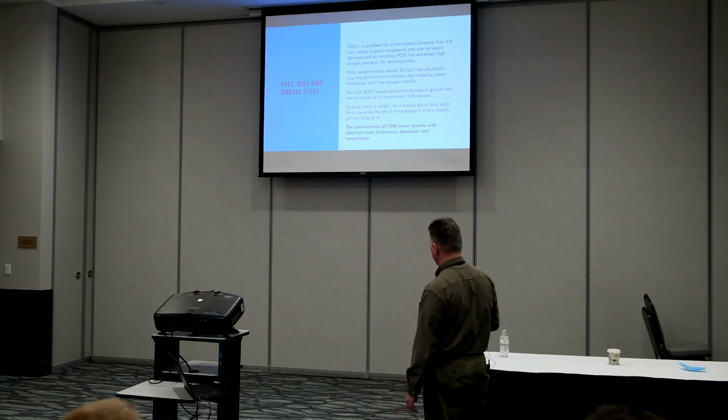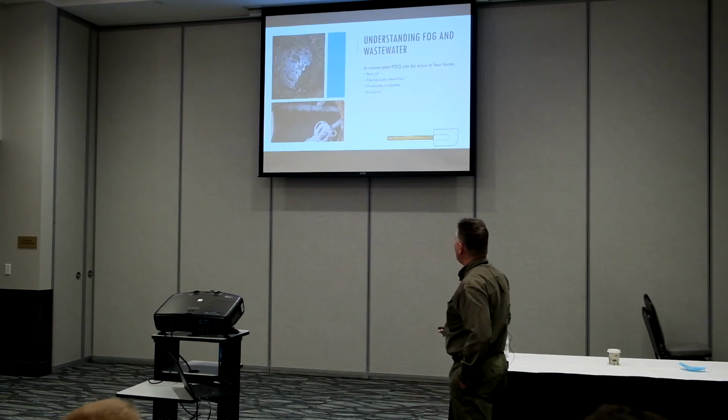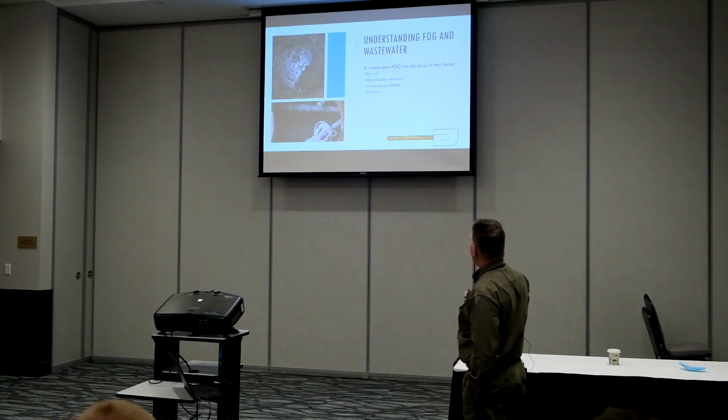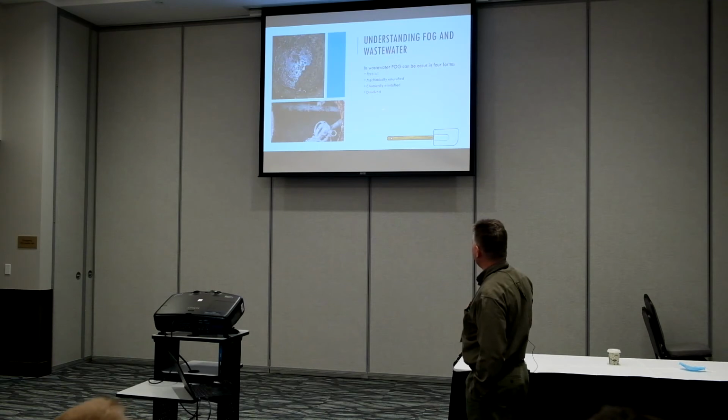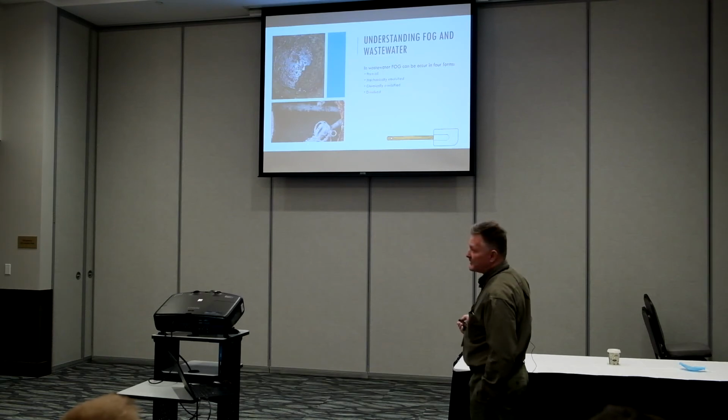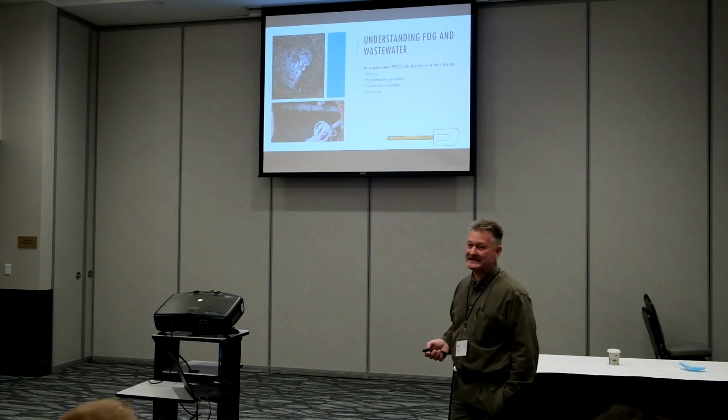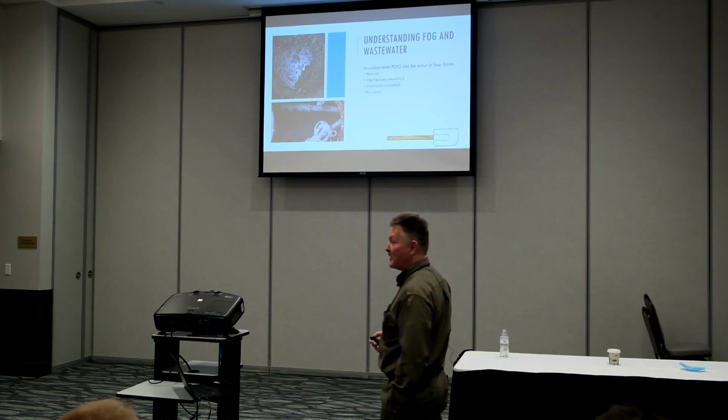And temperature has a big input. So understanding fat, oil, and greases comes in multiple forms that we're dealing with in the on-site industry. This right here, I snapped this picture a couple weeks ago at a restaurant that I was eating at, and I know over the years they have replaced their field multiple times. So I looked in their pump chamber going out to the field, and look at all the piping, everything's just coated with grease.